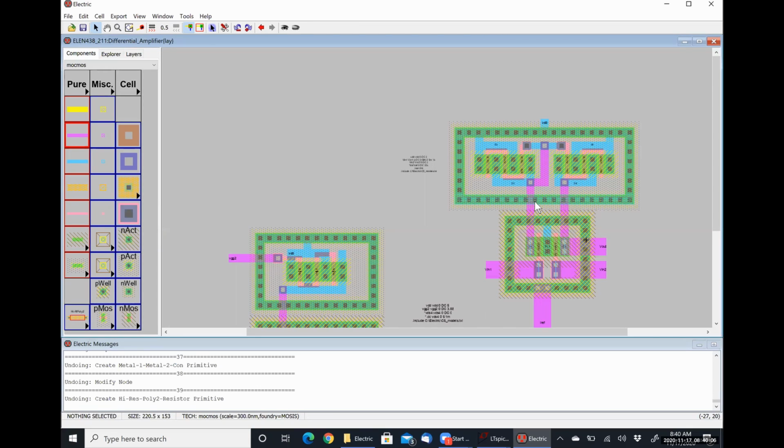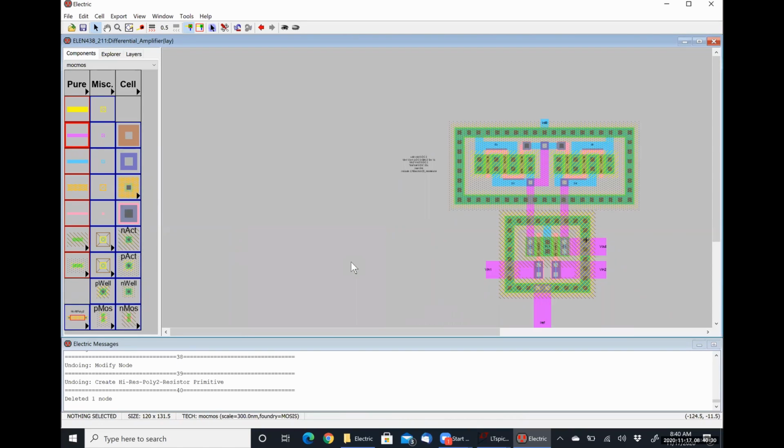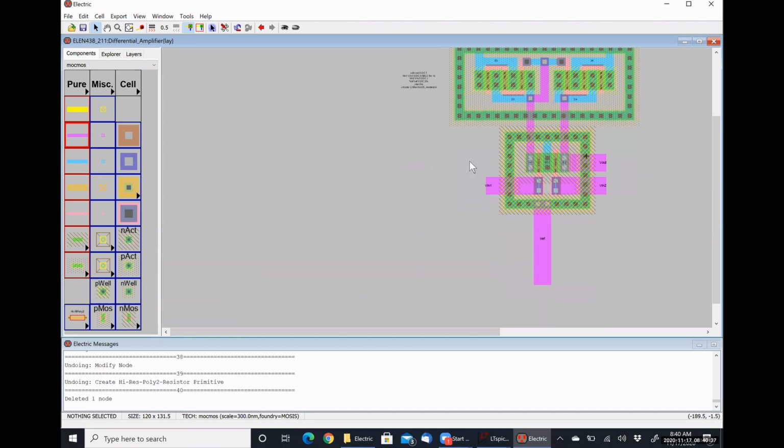We know that our current mirror outputs 20 microamps, and we know that our beta multiplier reference is supplying the 3.88 volts that we need to bias our current mirror to output our 20 microamps. So we've seen all three individual portions work in our layout. And when we chain this design together in the schematic view, everything is working swimmingly.